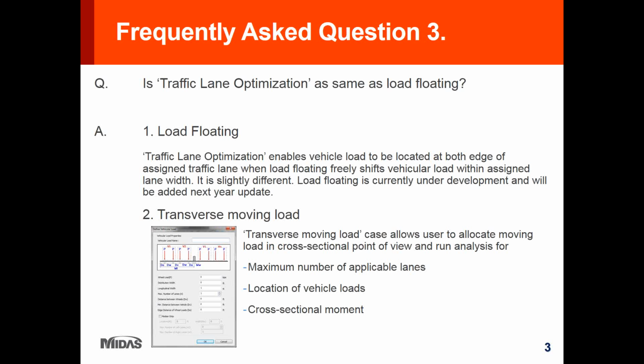In one of the project applications that I experienced before, I simply ran static analysis with all the dead loads, and once you turn on the legend, you have an idea of where the critical elements are located.